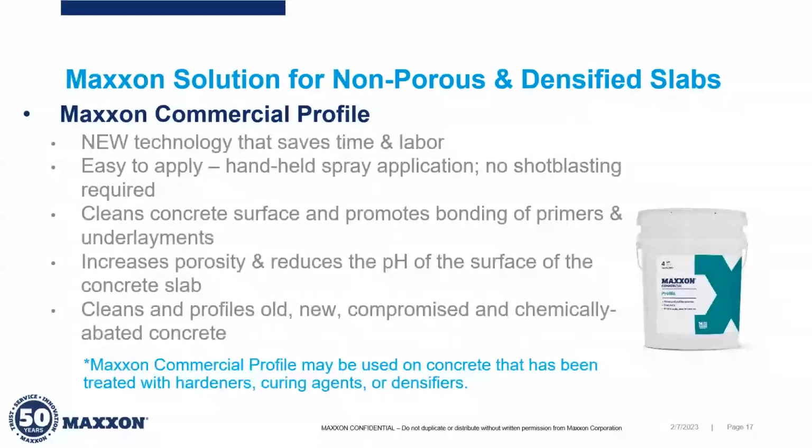So the big take home in this product is it must come in contact with the surface of the concrete. If there's adhesive residue, if there's paint over the surface, that's going to prohibit its ability to react with the salts in the concrete, then it will not work. So we want to make sure that there's nothing blocking its way from penetrating the pores of the concrete and reacting with the minerals in that slab. And as I said, it's going to clean and profile the floor depending on how long you leave it on the surface. Ideally, you can use this for heavily densified slabs as well.